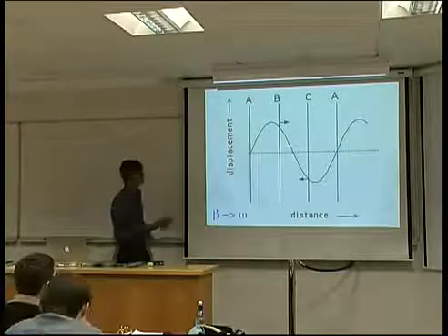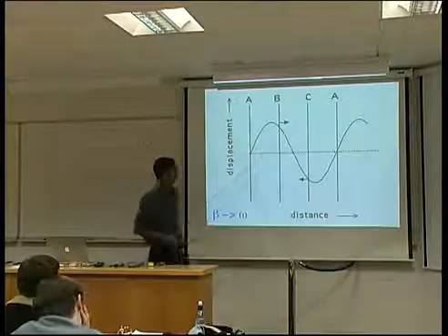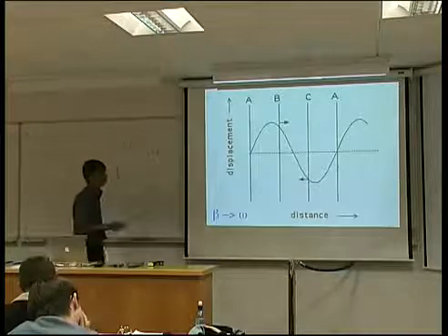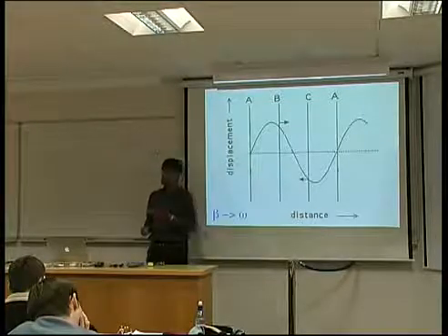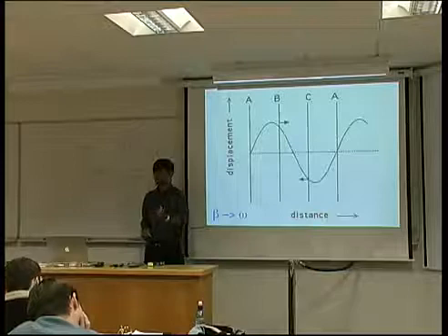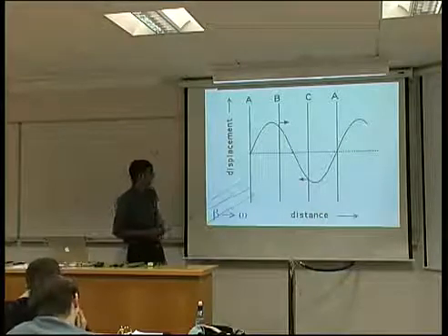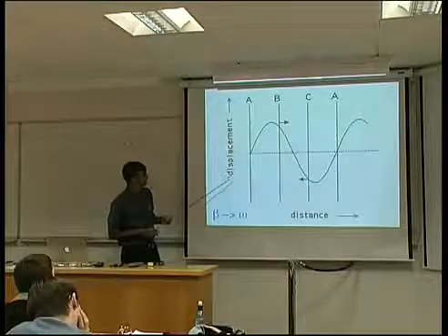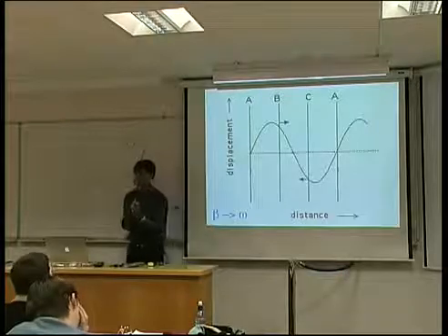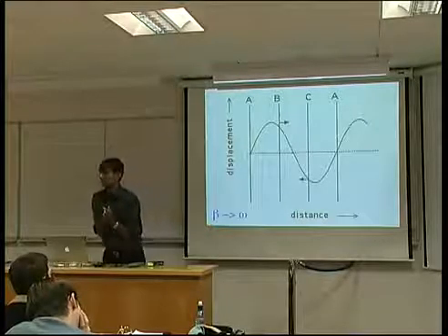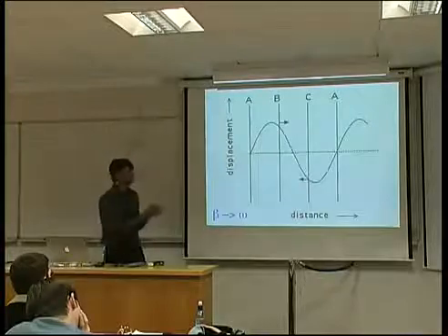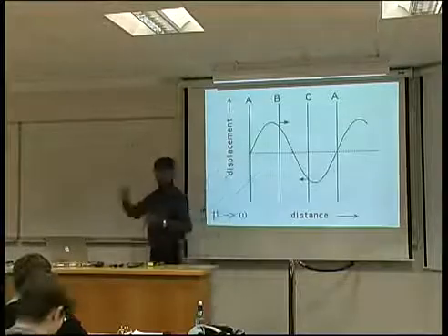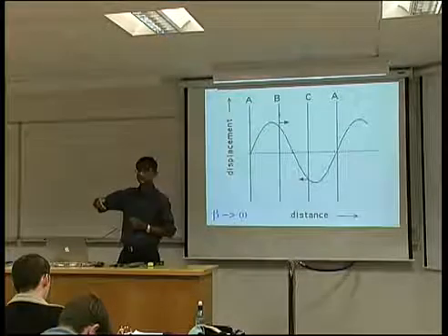So imagine that these are our planes of atoms. Okay, so the 1-1-1 planes. And you know that the 1-1-1 planes are stacked in ABC sequence, right? What happens is that you effectively get a displacement wave going through the system, so that these two planes coalesce. You double the atomic density in that plane. So you end up with an AB dashed, AB dashed, AB dashed sequence with alternate layers having double the atomic density.